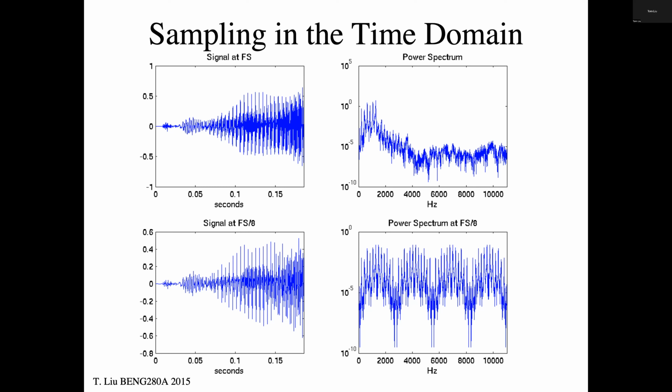and the radio frequency is coming from all different places, right? So you would get a bright blob just under your detector, your antenna. So it turns out it isn't the intensity as a function of position that you use with MR. You measure the phase of the RF coming out, and the phase of the RF, like how it's shifted in time with respect to the transmitted signal, tells you precisely the displacement of that signal in one dimension, right? So you do that multiple times.